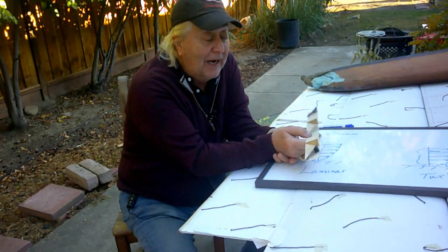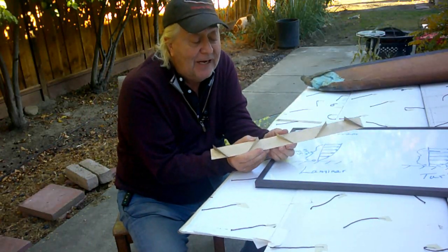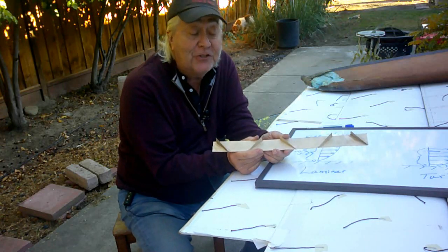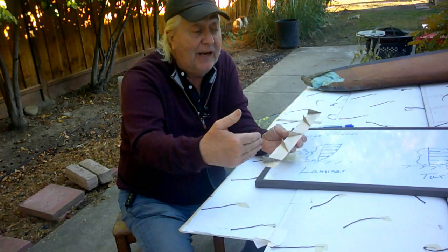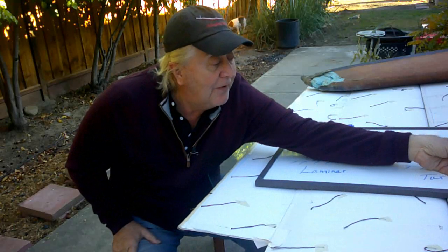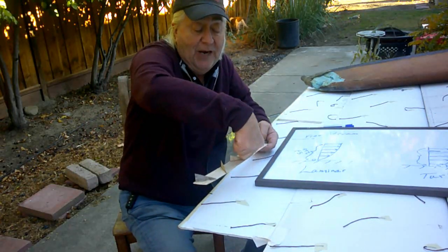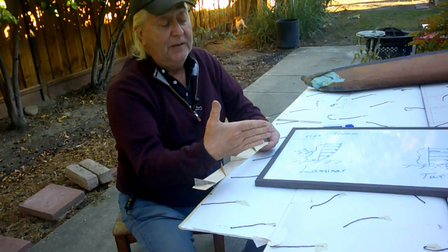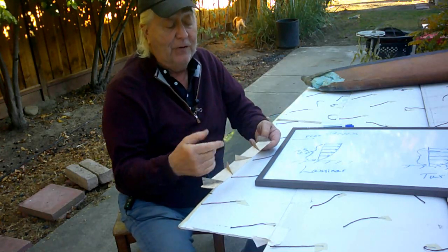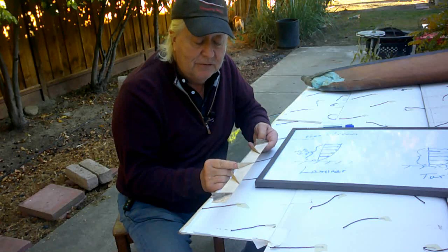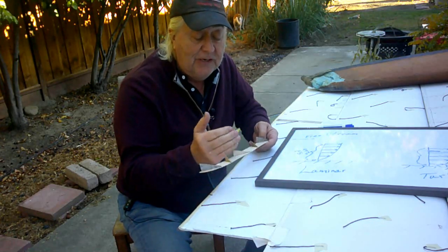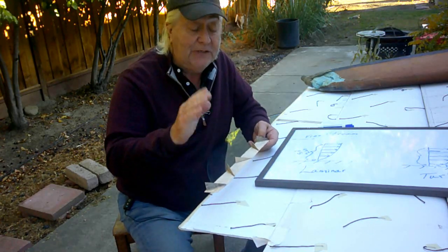So now we're down to this guy. What we have here is a set of standard, semi-standard vortex generators. Little triangles that are angled to the flow like this. You put those right up there like that. And as the flow comes in this way, this is like a little wing mounted at an angle to the flow. So it's stalled. This is like a wing that is stalled. Now these are at 45 degrees, so it's in a really deep stall.